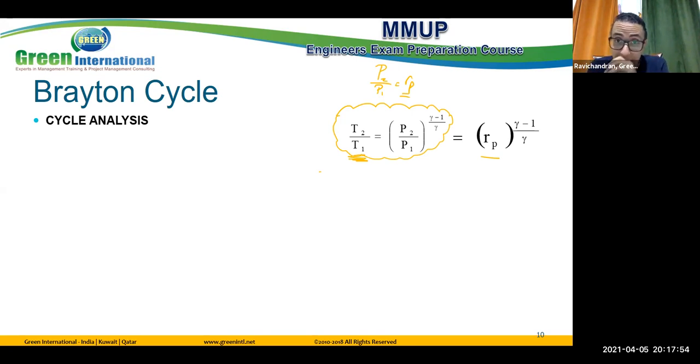Other cycles need H to be given. I saw one question on steam before, but in that steam problem H was not given. So the only way from my side is to consider the turbine range, or the steam, as superheated, approximately a gas. So I can apply it as a Brayton cycle, using Cp delta T as it is, because I can't imagine what the enthalpy value is. Otherwise, enthalpy should be given. Clear?